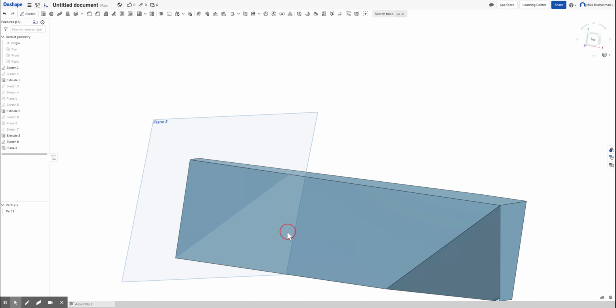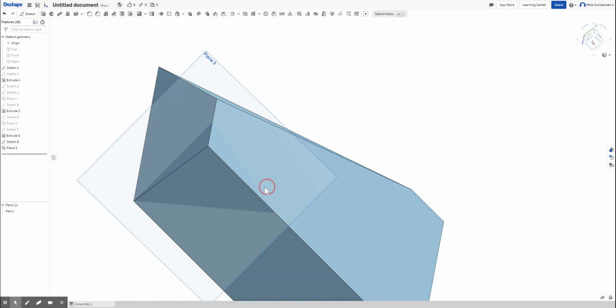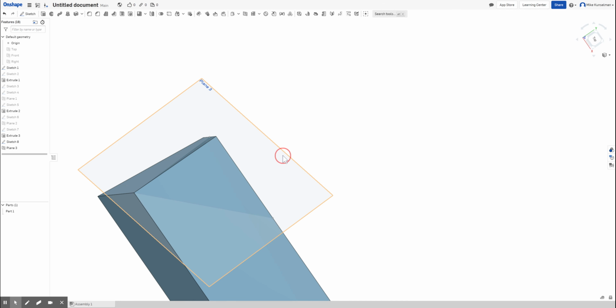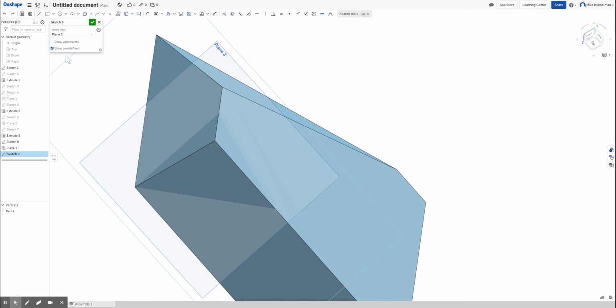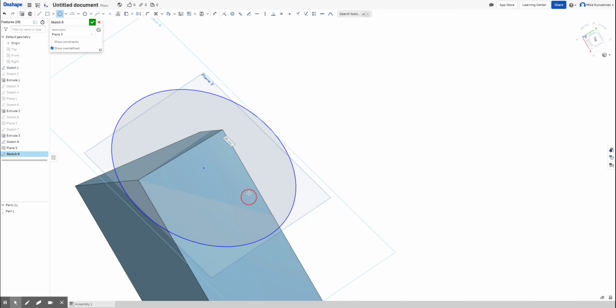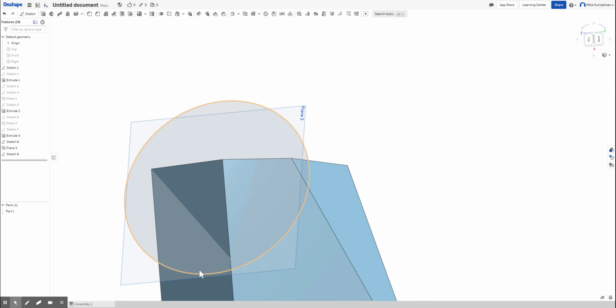Now, like I said, in Inventor, we used to be able to just split the plane. I haven't quite figured out an efficient way to do that in Onshape. So what we do now is just create a sketch on that funky plane. And then as long as that sketch has some shape on it that's big enough to cut this off, we're good. So, I wonder if we did even a circle. You know, the shape doesn't matter. We're just going to extrude it off. And then it'll all disappear. So let's hit OK. That's encompassing the whole chunk that we want to take off.